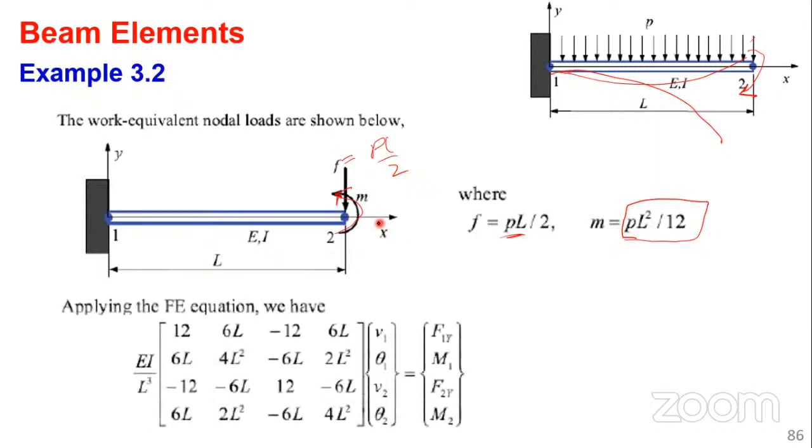So in the equation, we have just one element. So quickly getting the stiffness, of course, you know it. Then v1, theta 1, you have only two nodes, v1, theta 1, v2, theta 2. And you go and solve this equation. You invoke the boundary conditions. What condition do we have for this particular case here? You find that at the support, this head is fixed. Node 1 is fixed as a support. So we do not expect to have any vertical displacement. So F2y is equal to, not force, sorry.